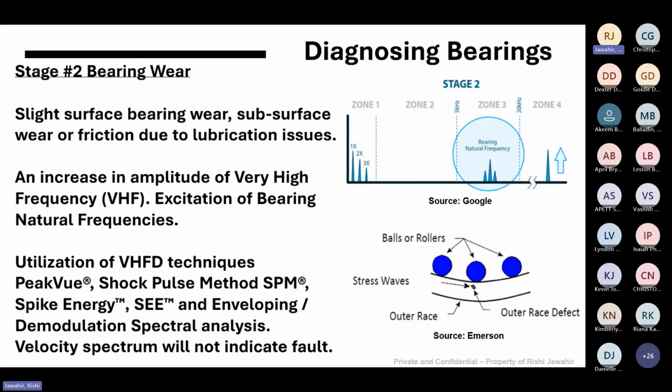So it comes back to your maintenance strategy, because sometimes condition monitoring may be done on a monthly basis. Some companies have it every 6 months or every quarter. Especially for your most critical equipment, you don't want condition monitoring done every 6 months or every quarter. At a minimum, start on a monthly basis. You may have vibration data being collected on equipment, and as defects start to increase, you have what they call bad actors.